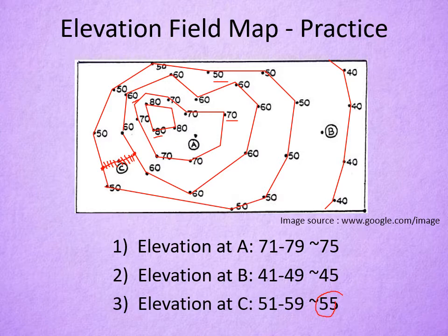Similarly, in this way you can measure the elevation of the B point and the elevation of the A point also. So for any point within this given area, after constructing the contour lines, if someone asks you the elevation or height of that point, we can easily determine the height or the depth with the help of these contour lines.